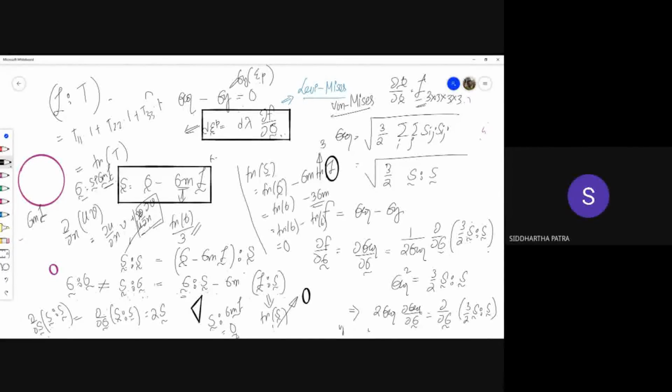Okay, so the deviatoric part and isotropic part are so designed that they are orthogonal to one another. And in principal coordinates, when you have three coordinates to represent stress and strain, they are three-dimensional vectors. The deviatoric stress and the hydrostatic stress are truly represented like two orthogonal 3D vectors, because deviatoric stress does not depend upon the hydrostatic part of the stress. So taking derivative of S with respect to sigma is as good as taking derivative of S inner product S with respect to S.